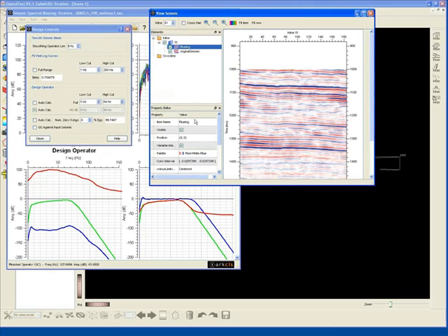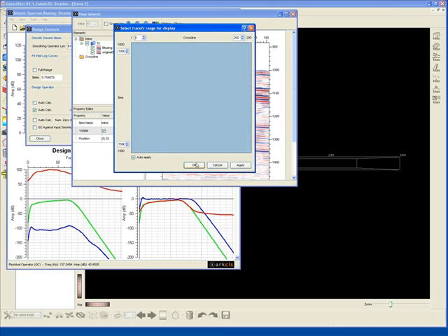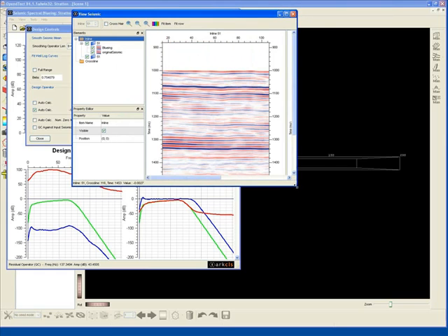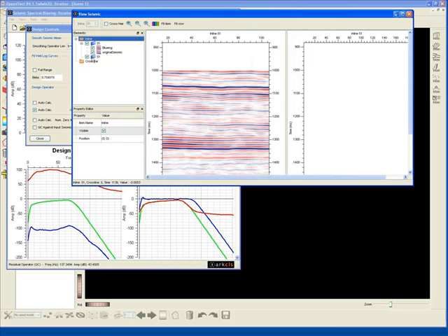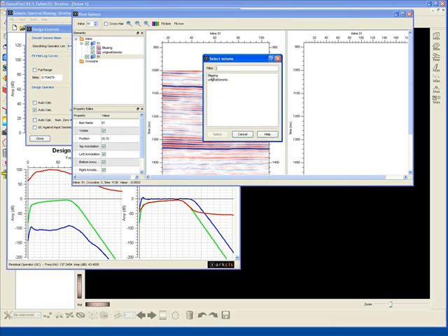That really is a brief introduction to the new facility. What I'm going to do before I leave this now is to show you, I showed you bluing on top of the original. We can also add a new viewport by clicking Add Seismic. That name will change in the final release, and we can add a new viewport which will appear out to the right. At the moment it's empty, but I can go down to the new viewport and add either the original or the blued volume. In this case I'll put the blued.